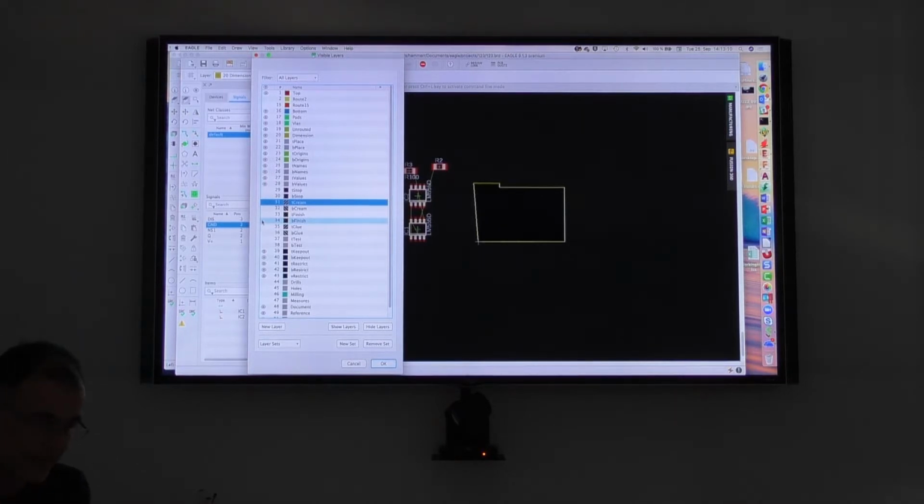And then we have glue layers, nothing inside by default, but if you think of such components like this one, they're also in bigger sizes. If you would simply mount it and put it onto your solder paste and you turn the board around, it will drop off. So sometimes it makes sense to glue this before you put it into the soldering.